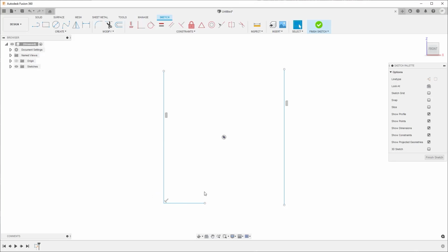Now if you attempt to drag the endpoint, it is locked or constrained to that respective constraint. You can do this for any number of constraints in your design, for example with this midpoint and subsequent perpendicular constraint. And as a quick tip, you can also temporarily disable this by holding Ctrl, or Command on a Mac, then continuing with your design. This feature helps you speed up your workflow by creating these constraints without any additional subsequent steps.